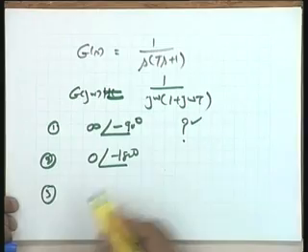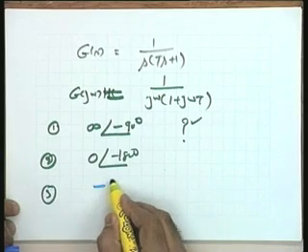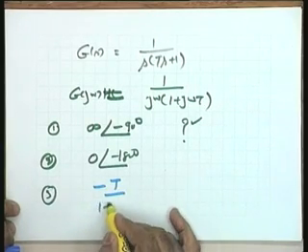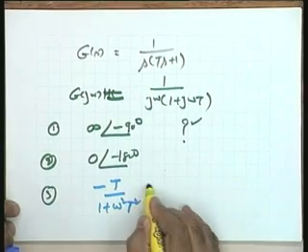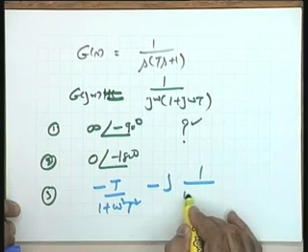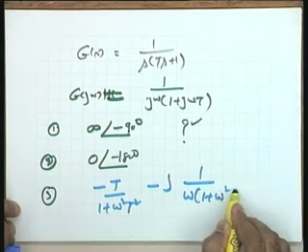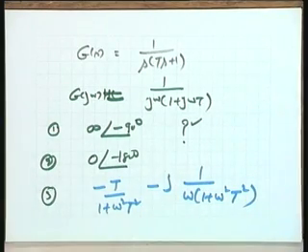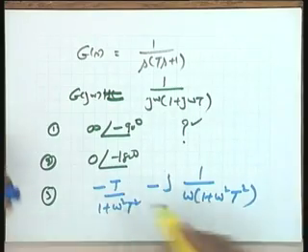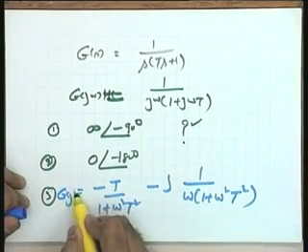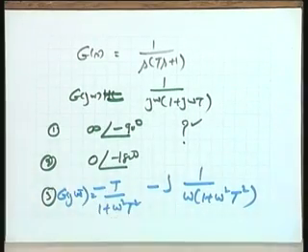Well, I think I have got the answer from the notes. Anyhow, you will be able to convert this into real and imaginary parts, and the real and imaginary parts are minus t over 1 plus omega square t square, minus j 1 over omega into 1 plus omega square t square. This is the function G(j omega) when converted into this particular vector.